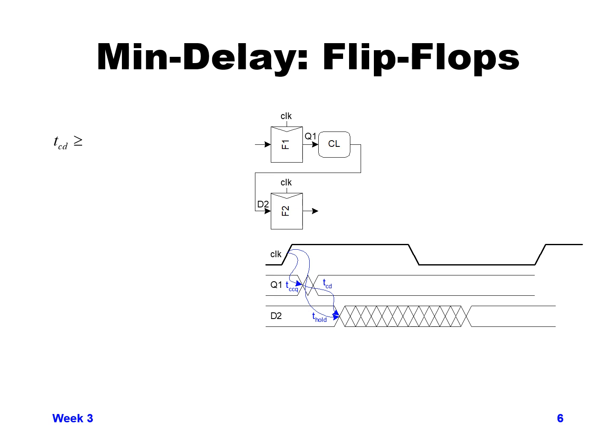In this particular case, we're showing two flops, F1, whose output is Q1, going through some combinational logic to produce D2 that goes into the input to the second flop, F2. Keep in mind, when we were talking about one of the parameters for a flop input, the data has to stay stable even after the clock edge switches high.